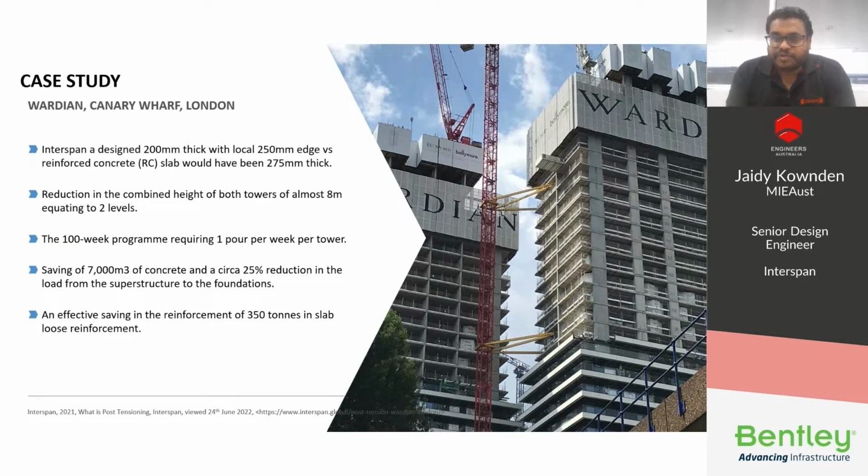The tight program of 100 weeks was only able to be achieved using PT, where we were able to do 1 pour per tower per week. The total savings was 7,000 meter cube of concrete and a reduction of 25% in the load at the foundation. We were also able to save reinforcement in the order of 350 tons in slab reinforcement.